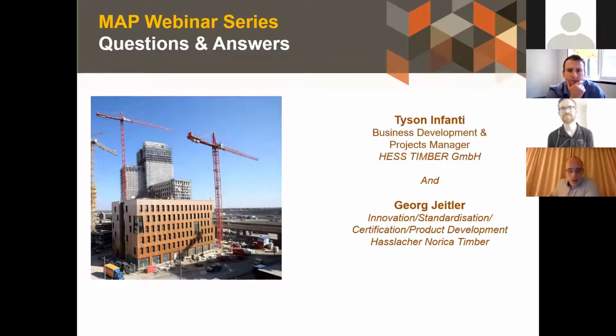Yes, for sure. The facade is load bearing. Not for the vertical loads, because for the vertical loads, the glulam columns are responsible. But they take the wind loads. They take all the wind loads, bring them to the columns, from the columns to the reinforced concrete beam, and from there to the ceiling, and from the ceiling to the back, to the concrete in the middle. Yeah, right.